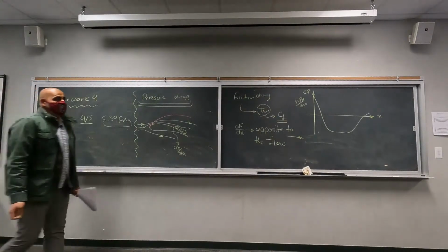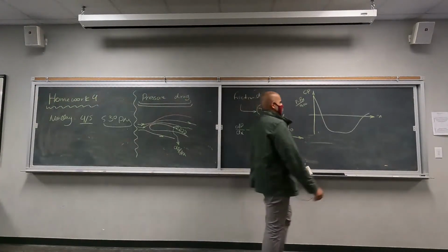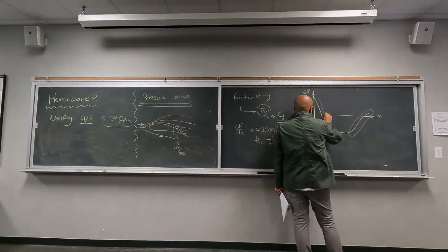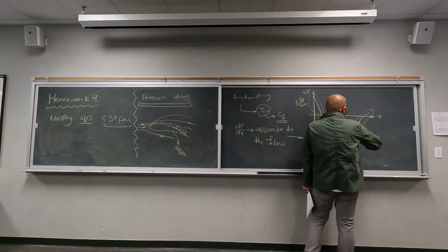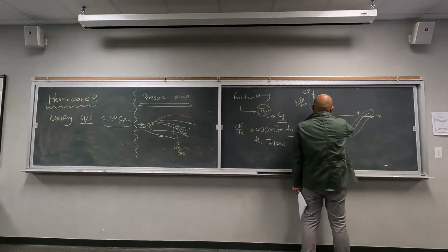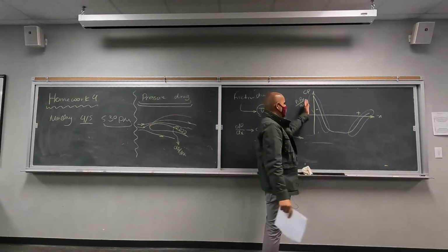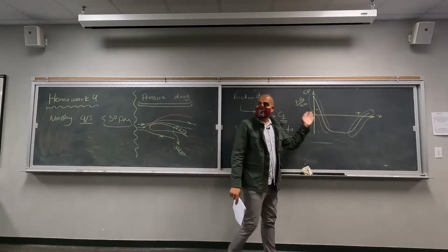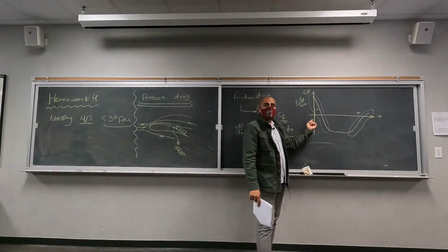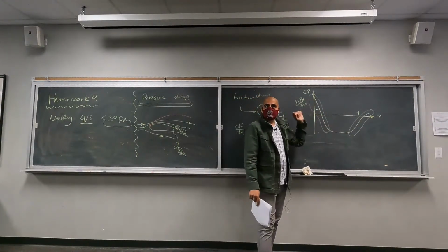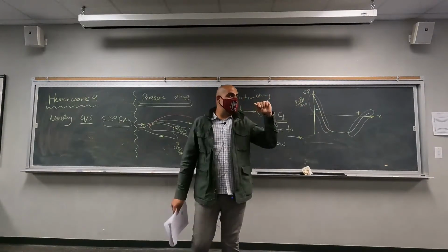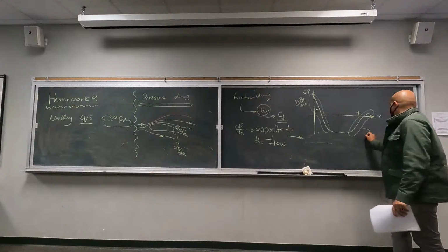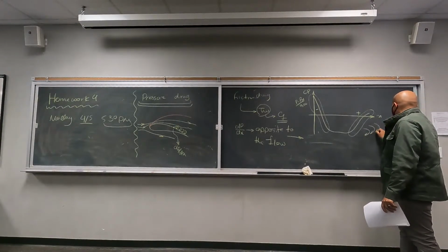As you can see here, the slope is positive, the slope here is negative, the slope here is positive. This negative slope is very consistent with the flow. Flow moves from high pressure to low pressure. But on the other side, we are going to have flow separation, so flow is going to move back.